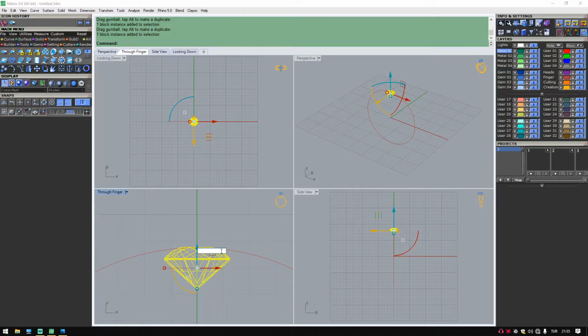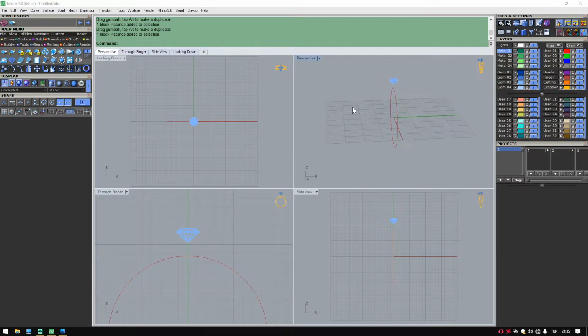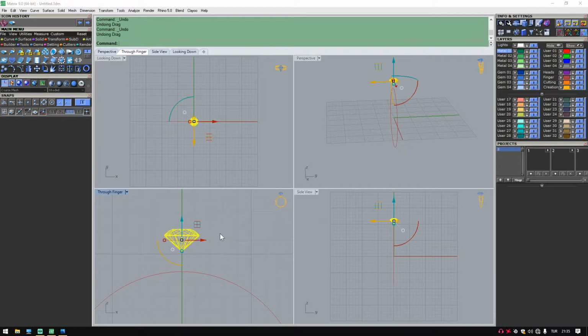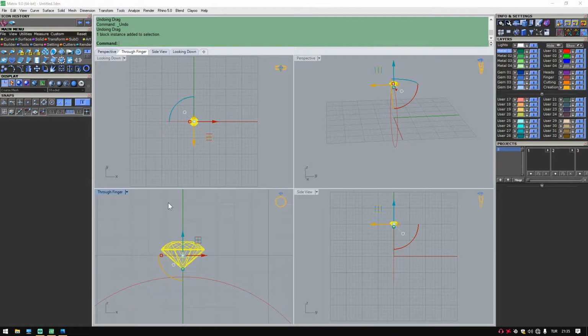Now, above boxed, here basically you can write specific millimeters. Like if you write 3 and hit enter on your keyboard, the gemstone will move upwards 3 millimeters. If this is okay for you, if that's what you want, it's okay. If not, you can go lower, you can go higher, or you can still continue typing stuff. Like if you want to move this 1 millimeter down, click the gemstone once, click this arrow once, and when it pops, you can type -1 for negative direction.